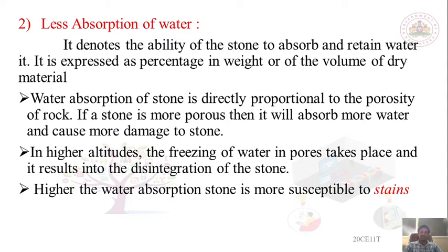The higher the water absorption, the more susceptible the stone is to stains. This is a very important point. You may get this question in exams also, like competitive exams. Which characteristic of a stone is the parameter where we can find whether the stone is going to be stained or not? A stain is nothing but a mark or a patch on a stone or other material.